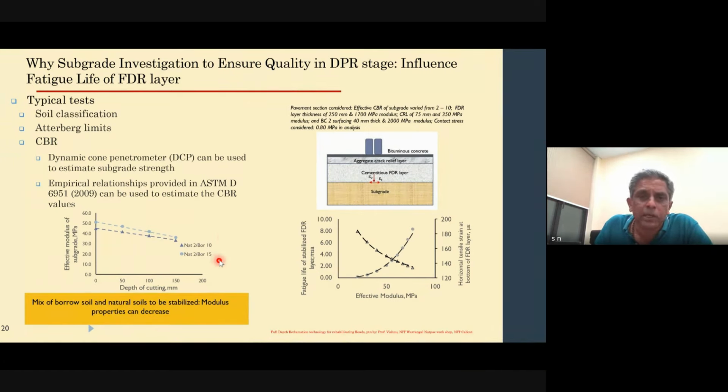Even though you don't use it for sample collection, you dig multiple trenches and make sure that the sections that you have collected upfront, a priori, where you have sampled your materials, the consistency of the sections remain the same as we go along. So just cut it open and measure the thicknesses and make sure that there is no change with respect to the one that you have collected your sample.